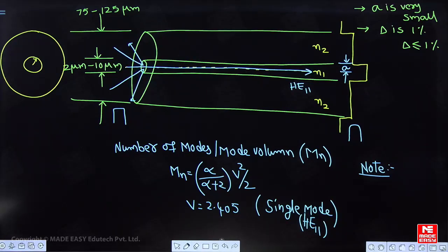Once you differentiate the step profile, you get an impulse; the magnitude of the differentiated value is infinite. In parabolic and triangular profiles we will do the same thing. I will explain those in tomorrow's class, and how you get each profile. The refractive index profile of the fiber core is given using alpha, the shape of the profile.